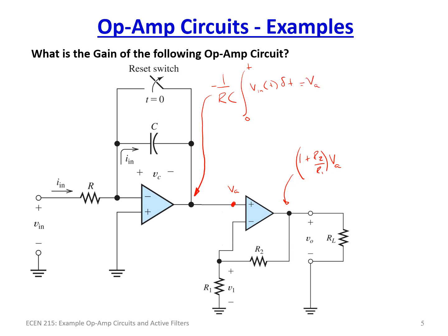So our total gain, which is also known as AV for this circuit, is minus, because it's still got the negative, 1 plus R2 over R1, because we're just going to do this in terms of the elements, not having any specific values.